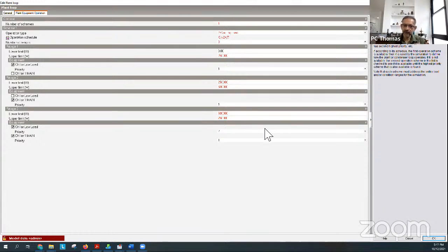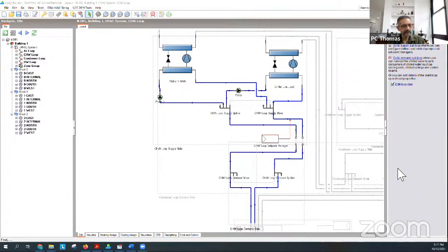If you don't do this, then your chiller numbers are rubbish. It will run a chiller as and when it pleases. If you have 2 equally sized chillers and both are prioritized, it might run 2 chillers flat out, and you will get double the amount of energy use. Sometimes you might get half the amount of energy use. It's confusing then.